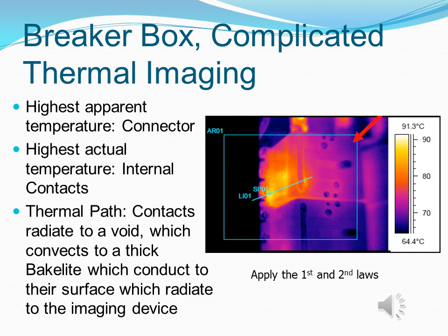And eventually all the heat dissipates, but more electric energy is coming in, the resistance gets higher, the heat increases, so you have a heat flow out to the thermal imaging device every second that this device is on. Only when it's off does it reduce down to ambient temperature, right? So this apparent 26-degree rise that you can see on the right side of that image, on the thermal contacts, will become a 50-degree rise in a year, and then become critical about 6 months after that, somewhere in that range, according to how it's used.